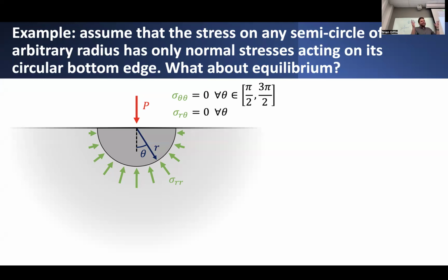Let's make the problem a little more tractable and take equilibrium on a small chunk of the plate. Cut out some kind of semicircle, and then pose our boundary value problem in terms of the distribution of stress on a finite radius semicircle. We could then come up with boundary conditions on the semicircle.